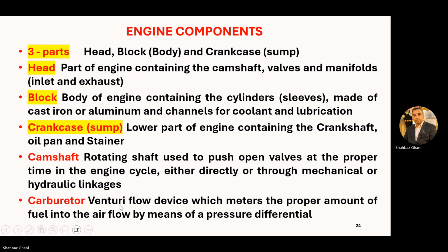Carburetor: venturi flow device which meters the proper amount of fuel into the air flow by means of pressure differential. A carburetor is an assembly in which we have a venturi flow device which meters the proper amount of fuel into the airflow by means of a pressure differential. All your old vehicles and conventional vehicles have this carburetor arrangement, but now with the advancement in technology, this carburetor arrangement has been replaced with fuel injectors.